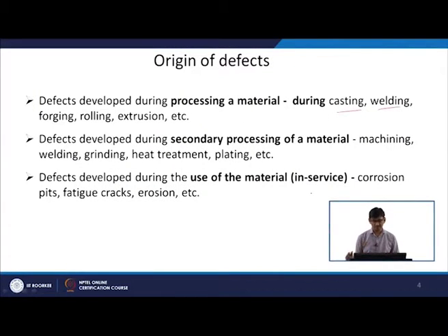In service, maybe due to corrosion, the material is exposed to a corrosive environment and corrosion is introducing some defects in the material, or due to fatigue loading, as we told you, during fatigue loading you can initiate some cracks, or erosion process. So, there are a lot of ways in which you can introduce defects during service. In these three cases we want to know whether any defects are there and what is the dimension of those defects.